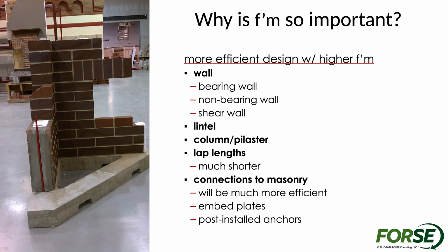Then I'd also say that there is an accuracy component to this as well, as we tend to rely more and more on finite element analyses for our projects. Using accurate values is very important. And so making sure that you understand what the f'm is for your masonry wall would be very important in understanding what the overall analysis and results would be for that masonry wall.